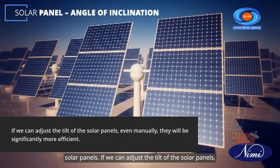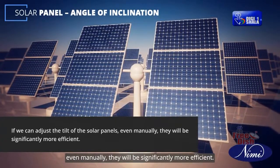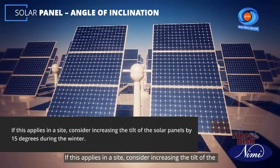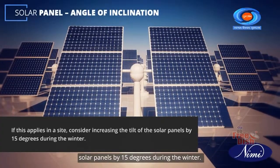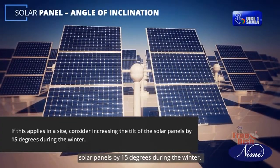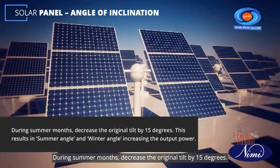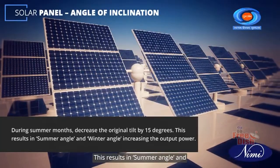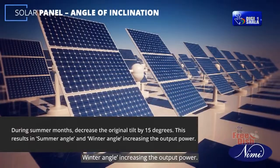If we can adjust the tilt of the solar panels, even manually, they will be significantly more efficient. If this applies in a site, consider increasing the tilt of the solar panels by 15 degrees during the winter. During summer months, decrease the original tilt by 15 degrees. This results in summer angle and winter angle, increasing the output power.